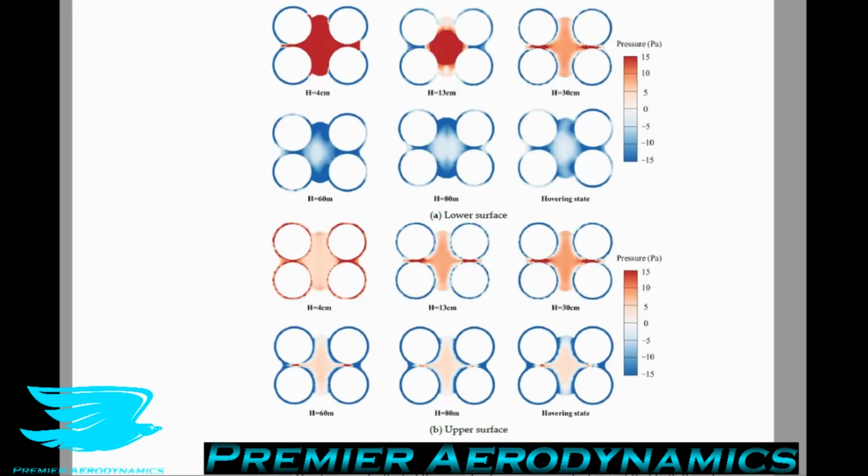Meanwhile, due to the limited size of the body, part of the airflow continues to flow downwards along the outside of the body, which reduces the pressure above the parent UAV. At the same time, a lower pressure area is formed at the nose and tail of the body. These result in slight decreases in lift. So in other words, because of this, you have lower pressure around these areas, the integration of the pressure around the entire UAV is lower.